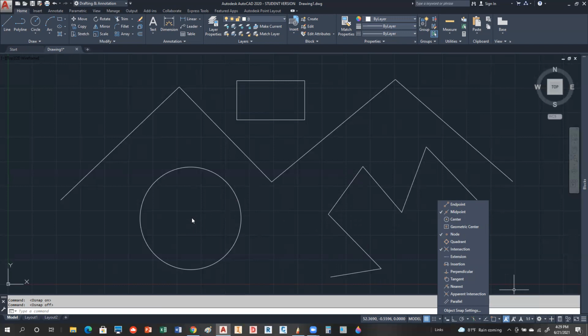That's what that's doing. This guy called geometric center will snap to something that's irregular or something that isn't like a circle. So for instance, it used to be if I wanted the center of this polygon here, I couldn't find it very easily. I would have to draw two diagonal lines, and where those crossed, that was my geometric center. This guy is a new snap, so he'll snap to that now because of the way that works. Oh, by the way, that has to be closed. So even though this is called a polygon right here, maybe that's an open polygon, you wouldn't have a geometric center. So it has to be a closed polygon. And it typically is going to have to be a P-line, okay?